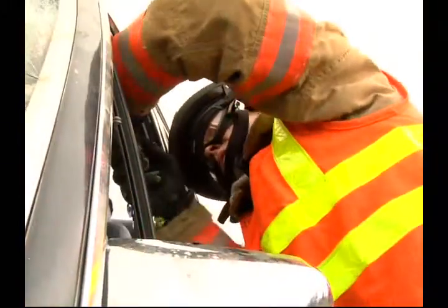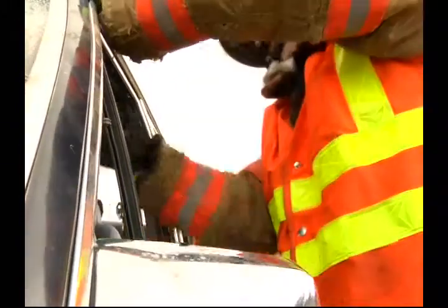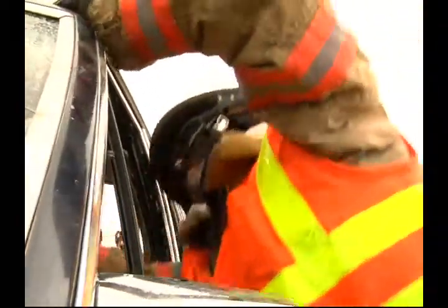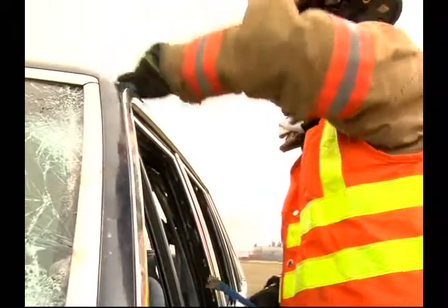Once you have identified the cylinders, use a permanent marker or other means to mark their locations on the outside of the car. This will remind you and your crew not to cut into this area during any roof procedures.